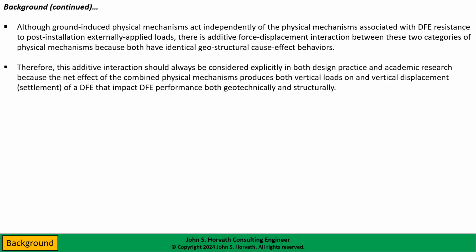And this is quite important because this additive interaction should always be considered explicitly in both design practice and academic research because the net effect of the combined physical mechanisms produces vertical loads on and vertical displacement in the form of settlement of a DFE that impact DFE performance both geotechnically and structurally. And I will, of course, illustrate these as we get into this presentation. And of course, this settlement can in turn impact the performance of a structure that is supported by DFEs.